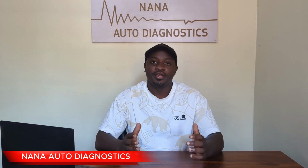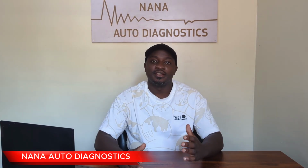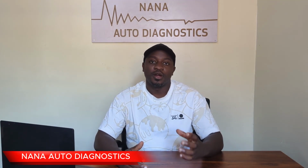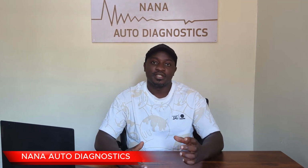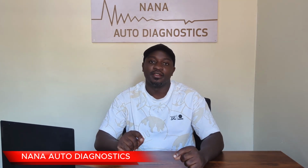A single wire is all that stands between your diagnostic tool and the vehicle's control modules in legacy cars. And some technicians out there usually treat this wire as any other wire in the vehicle. Understanding why your diagnostic tool is not communicating with the control modules starts by understanding the physics of that single wire, and that's none other than the K-line.